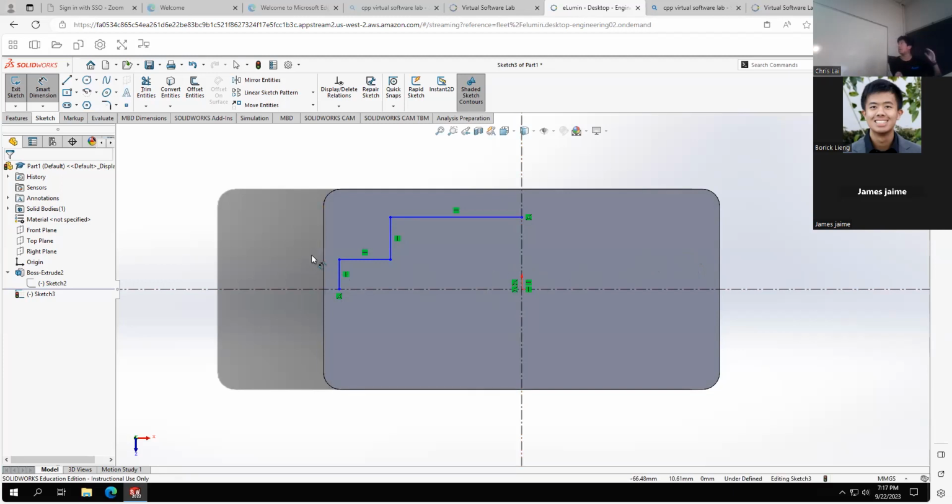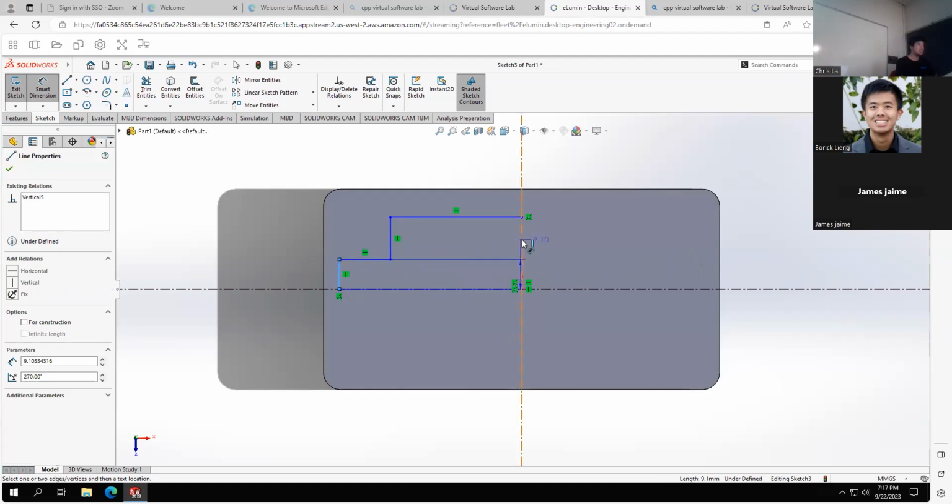For those of you who have used SolidWorks, there's a neat trick where you smart dimension from here, and then you click on the construction line and drag it over. It will show you the full length, or the mirror, if that makes sense. So for example, it says 108.49 right there. If I were to mirror this across that axis right now, the length between the point on the left and the mirror is going to be 108.49.